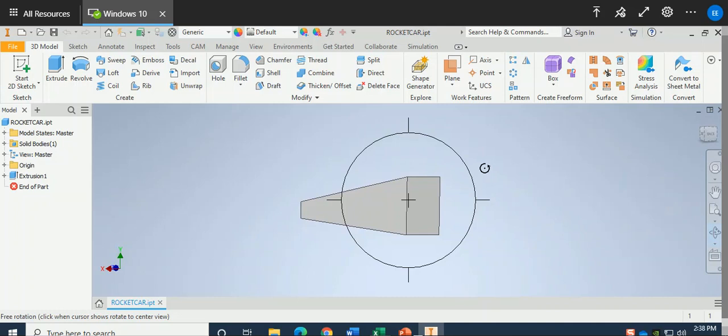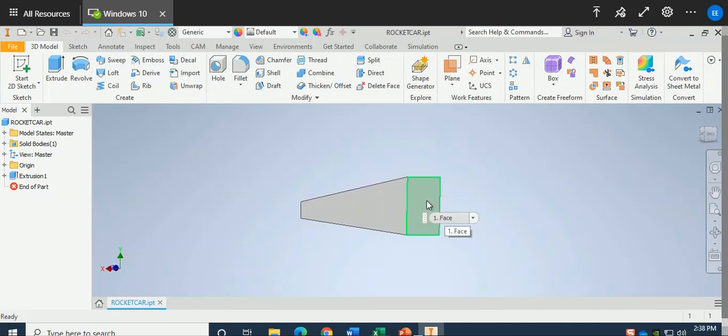So how do we do that? Press the right mouse button and click okay to get out. Select this plane first. This is what we do continuously. You learn from day one: any time you deal with Inventor part drawings, what do you do? You select the plane, then you create a sketch, then you draw, then end the sketch, and then exit and extrude, or create 3 dimensions.